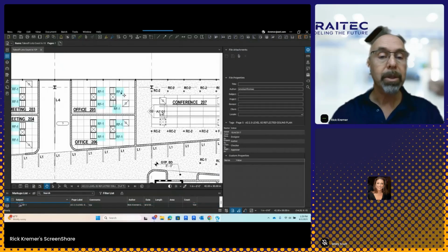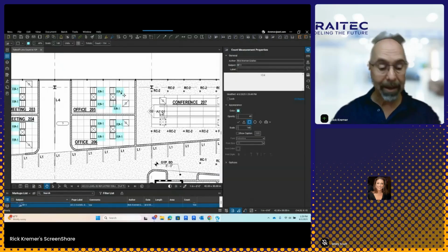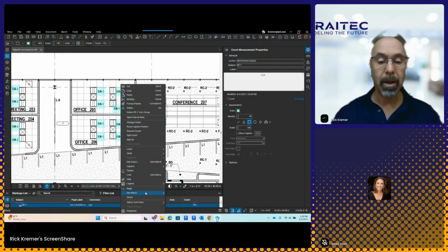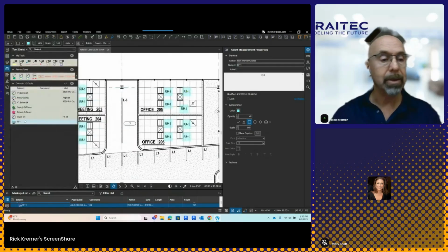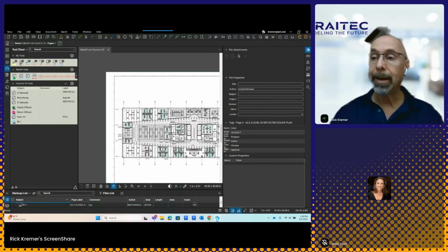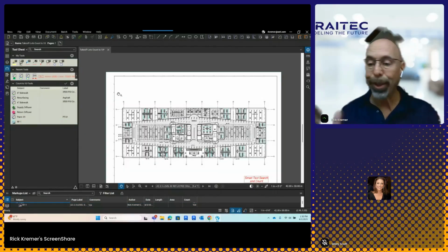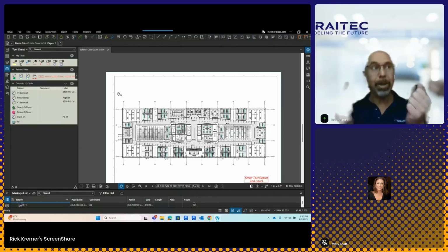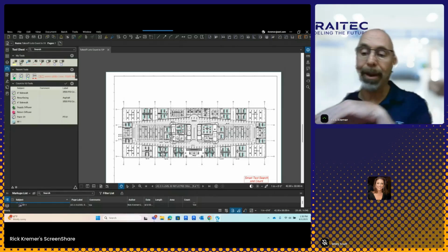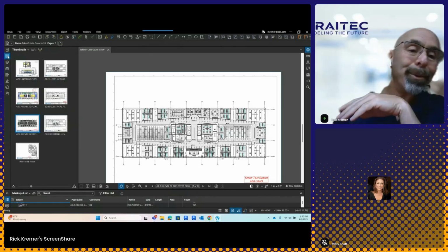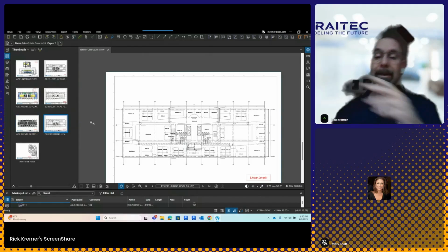And if I want to use this over and over again on my next takeoff, I'll right click on it, add to my tool chest, count to 10 tools, and here it is, RF1, so I can use this over and over again. Awesome. All right. We are just chugging through this. We are just not chugging, we're going fast. This is great. All right, let's go through real quick and take a look at another example.